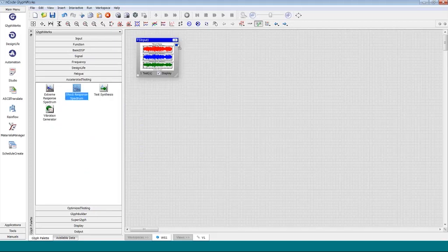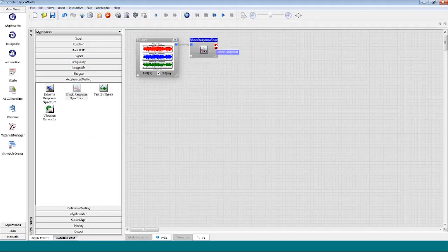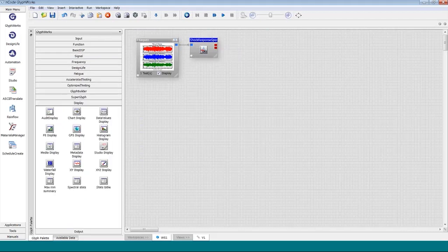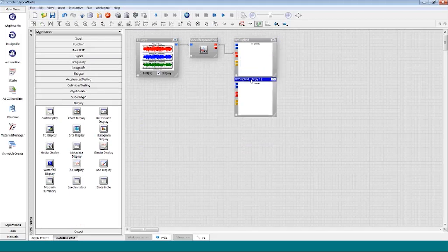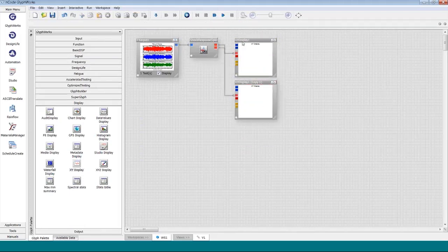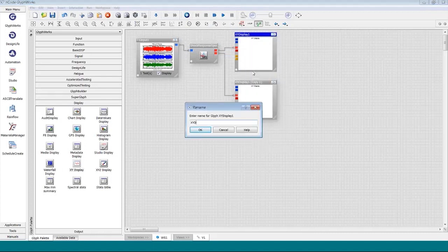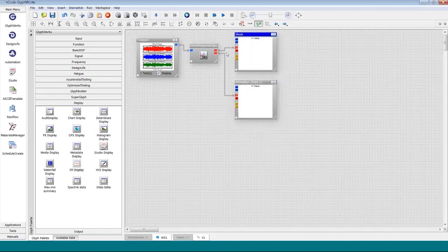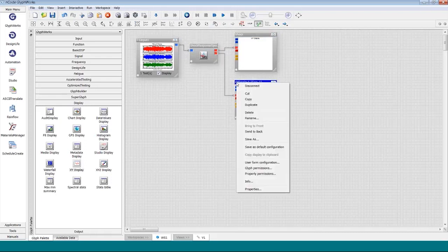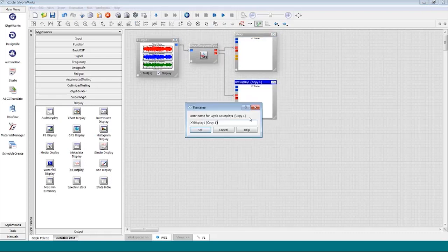What we're going to use instead is the concept of the frequency shock response spectrum calculation. And this will give me 2 outputs, the shock response spectrum and the fatigue damage spectrum. So I'm going to go ahead and calculate these, and put on a couple of display glyphs to capture these answers. I'll duplicate this one down here, and just as a naming thing to keep these straight, I'm going to call this top one shock, renaming the glyph. And the bottom one was the output for the fatigue damage, so I'm going to call this fatigue.